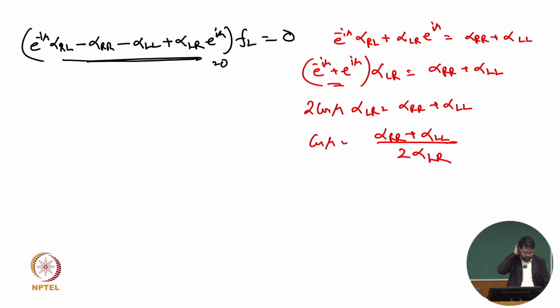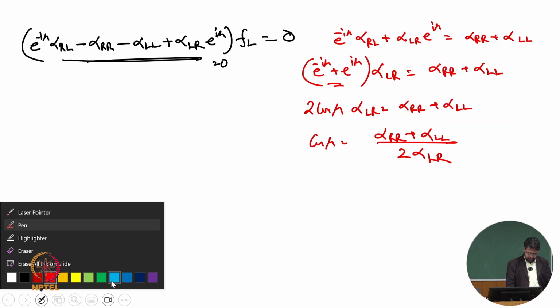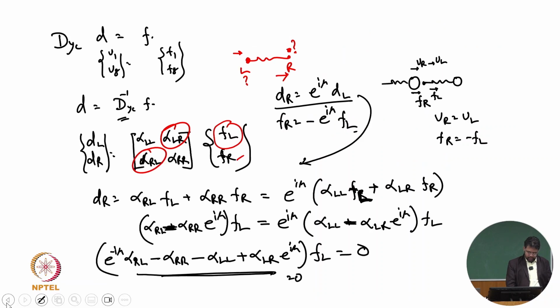Yeah, in the receptance matrix, we can see another very interesting thing as well. That is, if we try to feel what is lambda LL and lambda RR. Now think, what is lambda LL? If we are not applying any force in the R, how much deflection will we get if we are applying force on that node? Exactly. That is lambda LL. If we are applying the unit load, how much will be the deformation there? And otherwise is lambda RR.